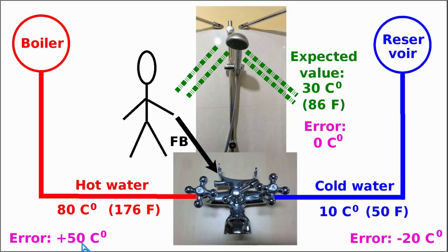When the error we calculate is really large, like in these two cases, then we know that we are very far away from the expected value. In this case, our controller will change or adjust these two valves, which are, as I mentioned, the control element, so as to minimize this error as fast as possible and get close to 0. When we reach a 0 value of the error, then we are sure that our output is exactly our expected value.